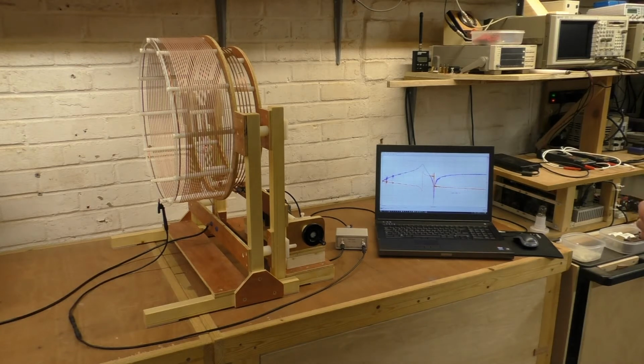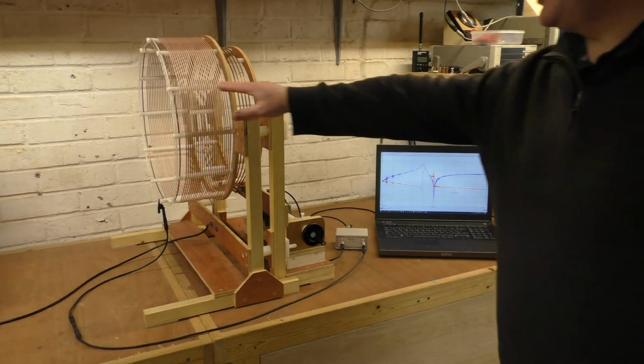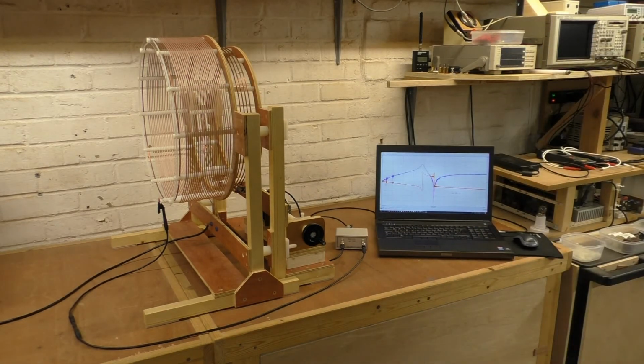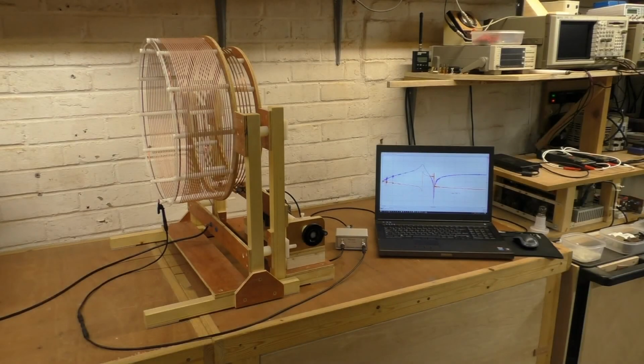We also know that there is voltage magnification going on in the secondary coil, and that is also determined within safe limits for this device. A good way to start off the experiment, if one is unclear, is to put an attenuator in there, say a 20 dB attenuator, and also to reduce the input.